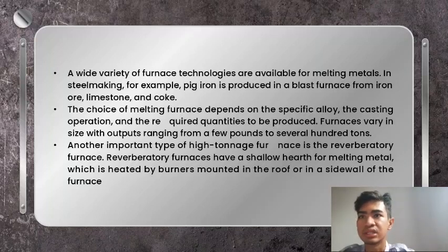Melting in a cupola furnace dates back several centuries to the old cast iron units that were operated with hand pump bellows. Modern cupola furnaces may no longer use many manually operated bellows, but they remain one of the most efficient sources for the continuous high volume of iron needed to satisfy high production levels in manufacturing operations. The cupola furnace is basically a simple cylindrical shaft furnace that produces intense heat generated by blowing air through a hot bed of coke.